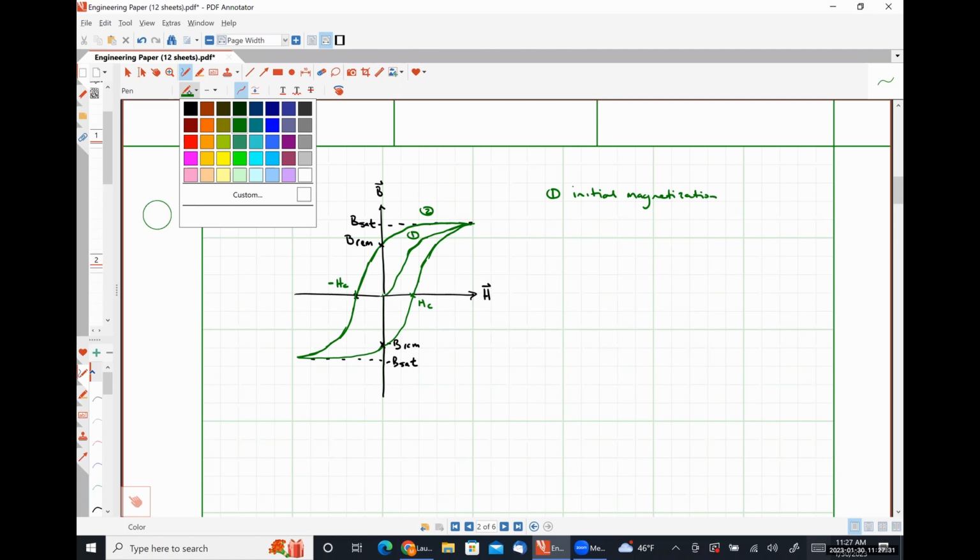And some materials in this magnetostrictive region experience a stress due to an applied magnetic field. So it's similar to piezoelectricity, except that it's a magnetic field that's doing it. Now, what's interesting is that this stress can cause the material to elongate or mechanically deform.